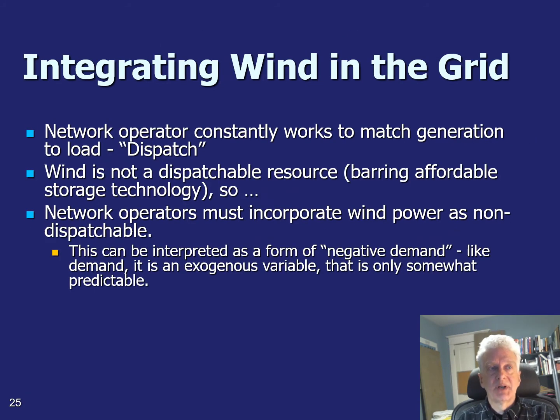So let's talk about the concept of power dispatch. When you're operating a power grid, the power being generated and fed into the grid has to exactly match the power being drawn by all the customers combined, all the loads. And you can track with metering how much demand there is. You've also got past history to say what you expect that the load is going to be, but it does vary through the day. So traditional dispatchable sources, the power grid operator has just simply called or scheduled to say this plant should be on at this % power at this hour.